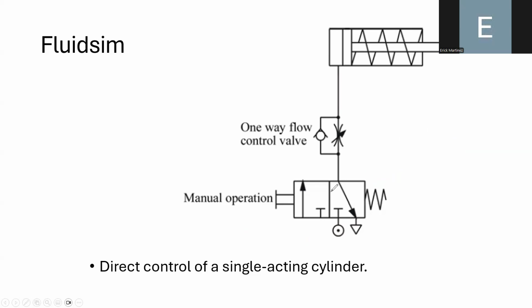So here you can see that we have two positions. So we have here the diagonal and we place a 2. And also you can see that we have one port right here, another port right here, and also another port in this part. Okay. So you can see that in this case, in port C, there is no airflow due to this symbol. And also you can see that the air in the first position is moving from port A to port B. But in the second position, we have again port B, and also we have here port C and port A.